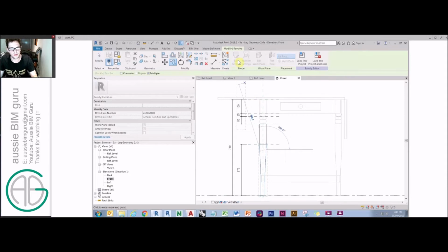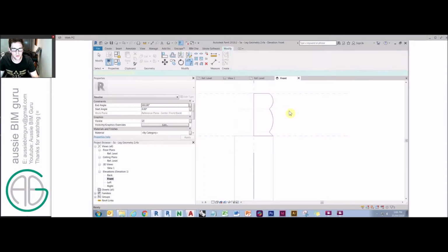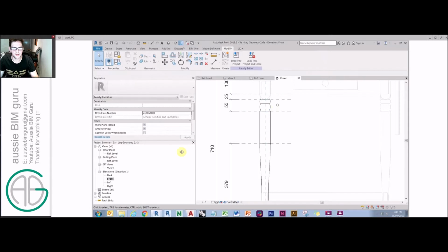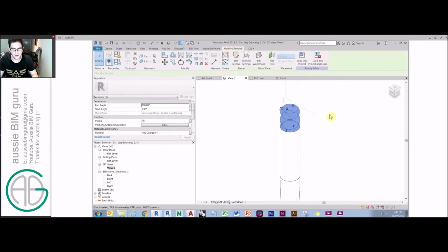Okay, now we'll do another revolve, and instead of starting a new revolve, you can just copy an old one if you so choose, and then modify it from here, because the other one will be left alone at this point. Okay, so we'll do our boundary, which is here to here. Take our middle boundary line, and then we will just pick these three lines without locking them. And likewise, as it did before, you'll see that it'll revolve that profile around again. So quite a handy tool for relatively ornamental objects.